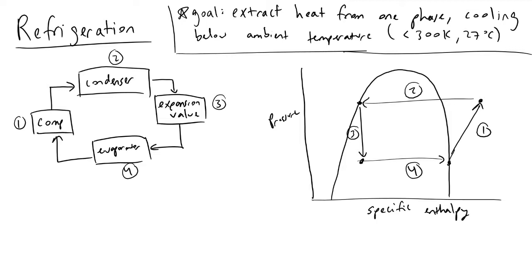And what happens is your Freon will do a phase change from a vapor to a liquid and liquid to a vapor. And what we know intuitively about vapor is that a molecule will have more energy in the vapor phase than it does in the liquid phase. And so as we vaporize a molecule from a liquid phase into a vapor phase, it must grab thermal energy from its surroundings to do that. And as it grabs the thermal energy, it results in lowering the temperature of some unit.